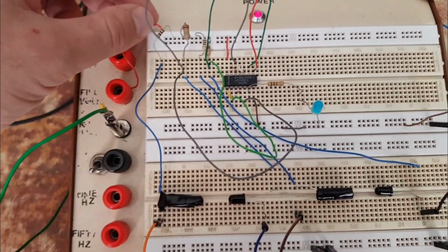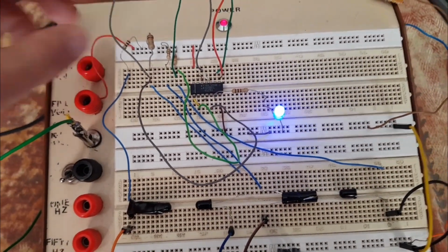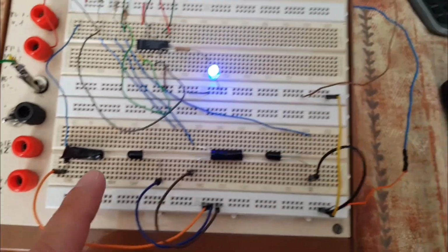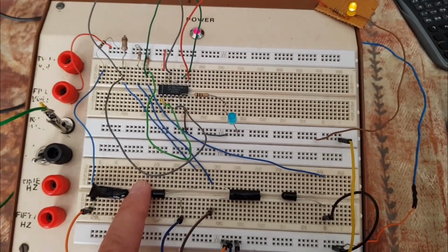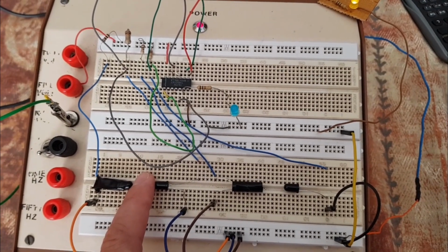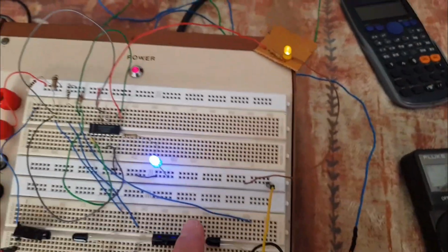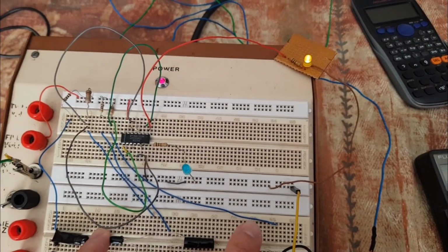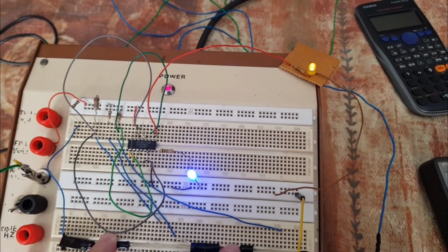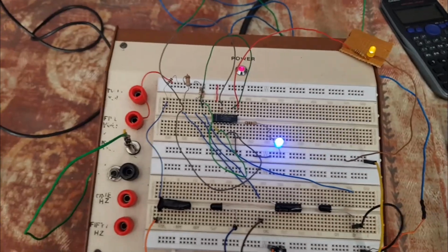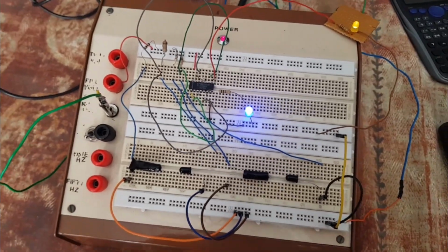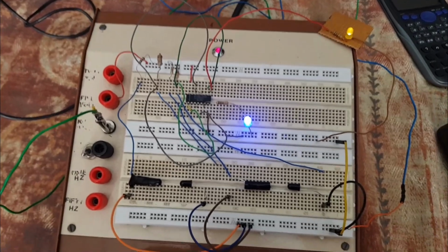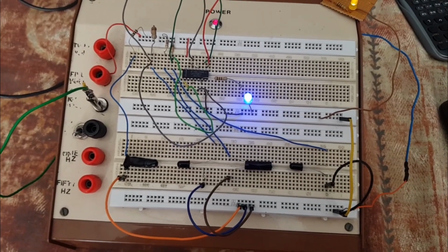If I turn it on, the logic should remain the same, where both are on when both are receiving light. When I block S1, the output at pin 6 should go off. When I block S2, the output at pin 8 should go off. And if both are blocked, both should come on again. And therefore the logic works. We can also now see how the voltage changes when we wire up an oscilloscope to the sensors.